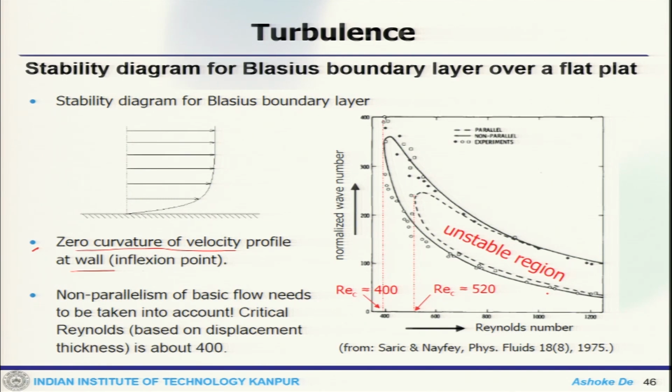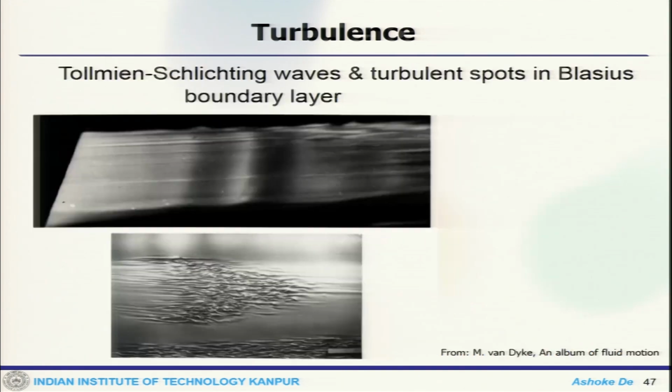so if you take a different flow regime, whether it is a simple flow between two parallel plates or a boundary layer flow, you can demarcate through linear stability analysis which zone is stable and which is unstable, and the Reynolds number at that point would be the critical Reynolds number, which tells you what the situation could be.